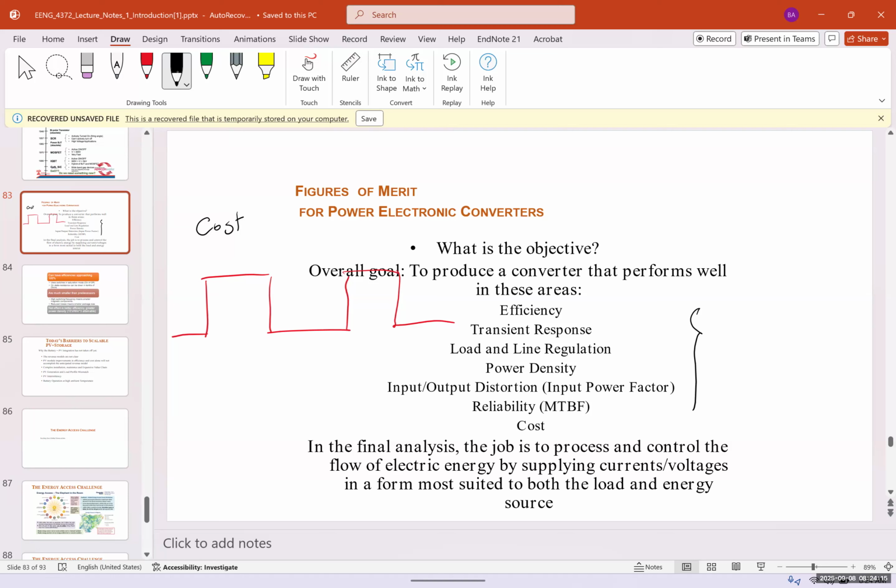So if you want to build a grid connected inverter, by the way, grid connected inverters are usually the highest quality, because you have to be able to match the grid frequency in real time, match the grid voltage in real time, match the power factor, everything, and be able to cut the power if you need to. So it's a unidirectional system sometimes, and sometimes you need a bidirectional system to be able to get power from the grid and give power back to the grid. I'll give you one example.